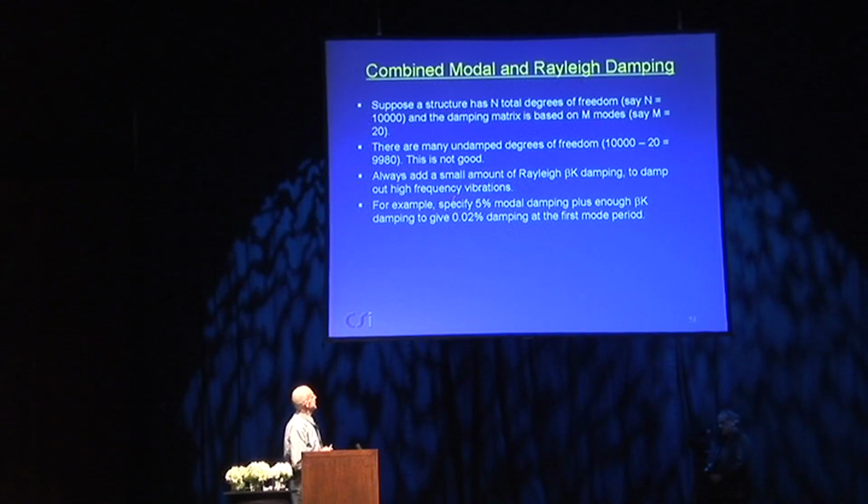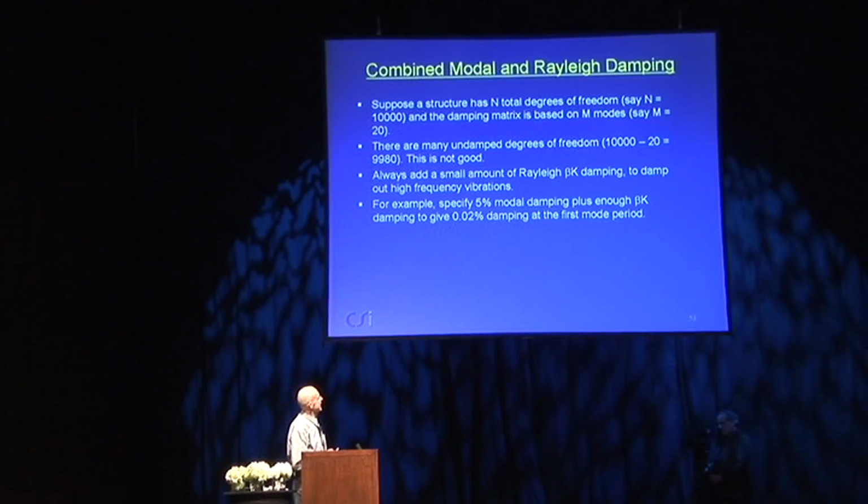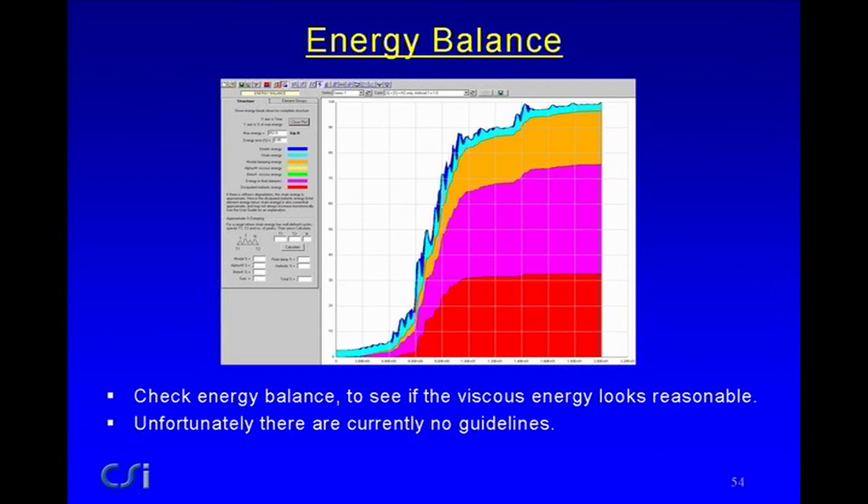So what we recommend is you add a very small amount of Rayleigh beta K damping to damp out the high frequency vibrations, just a very small amount. And this also seems to work well. It doesn't add anything significant to the total energy dissipation, but it does stabilize the solution process.